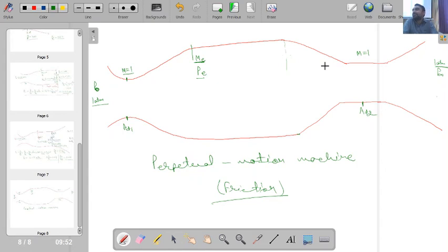There will be formation of shock wave. So these two things we have not accounted yet; we are considering an idealized situation, but the ideal situation will not be there. One thing is friction will be there, and another important point is that here we are having a sharp concave corner, so here I will be having formation of shock waves.